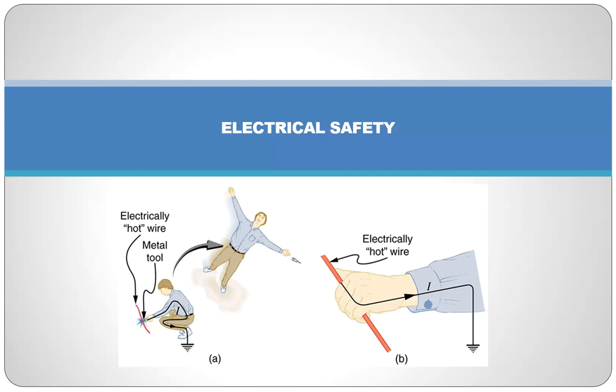It's measured in somewhere between, if it's wet and nice and lubricated skin, it lowers the resistance across the skin, so it might be just a little over a kiloohm. If it's dry skin, it'll be maybe 100 kiloohms or so. So wet skin versus dry skin, very big difference in resistance. But still, think about the numbers I quoted.